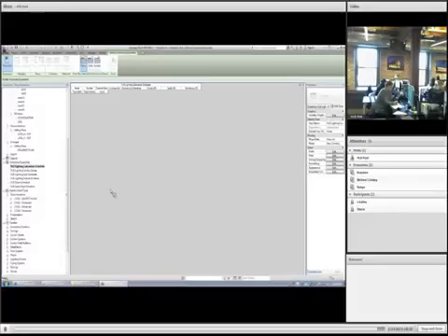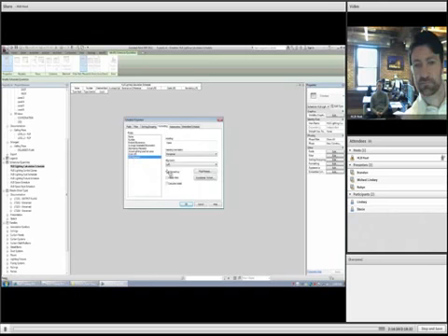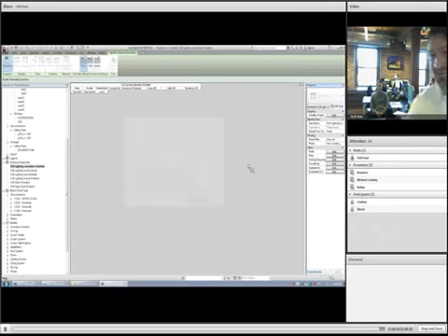I think you all will really like it as well because it's going to give it to you by space. You're going to put in your desired illuminance for that space, and if you're not meeting it, it's going to give you a color. It's saying, red, you're not there. Or if you're going over on your power density for that space, conditional formatting, exactly. That's all within the formatting, LPD mismatch, in this case conditional format. And if it's less than or equal to a certain amount, it's pretty cool. Conditional formatting brings out the nerd in me for sure.